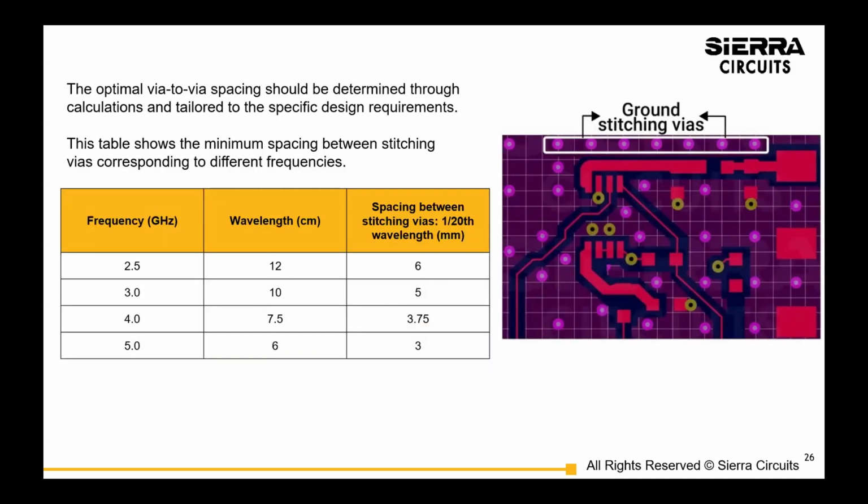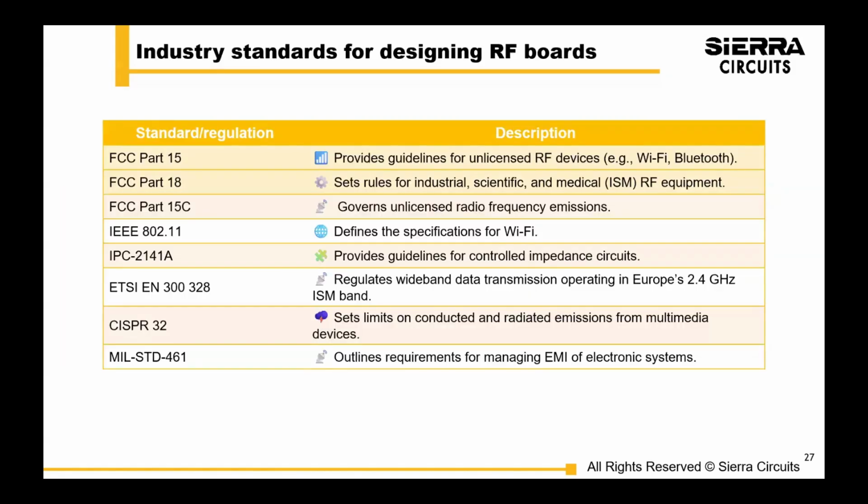I get a lot of questions about, from a manufacturing standpoint, if we have different via sizes, does that increase cost? Not anymore. Most drill machines already have all the canisters of drill sizes, and the machine just swaps out whatever drill size is needed. It used to be that setting up the tooling for your job, if there's n number of different drill sizes, could be a little bit more time consuming and labor intensive, but that doesn't really exist anymore today. So don't worry about that.